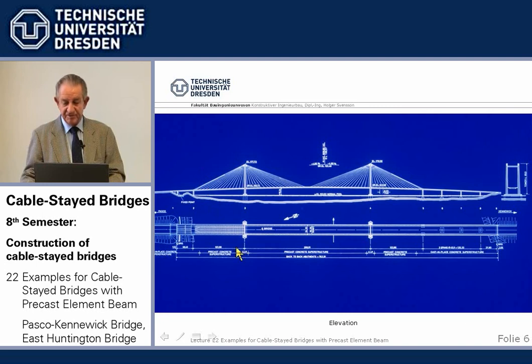The bridge itself, it's hard to read, I know, has a main span of 300 meters. It was 1,000-something feet, but we designed all that, of course, in feet and inches. But 300 meters is good enough for precast. At that time, it was a world record for a concrete cable-stayed bridge by itself. Today, there are, of course, longer spans, but with a heavy precast, I think it's still the record. We have a simple tower with vertical legs and a strut.